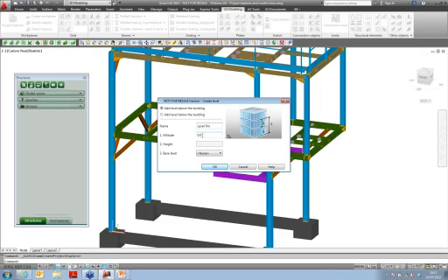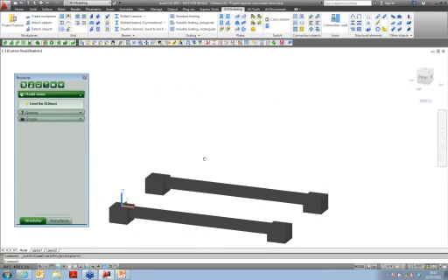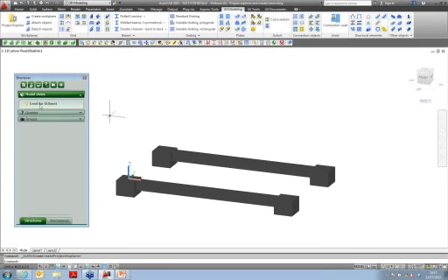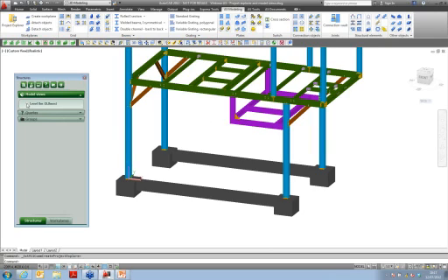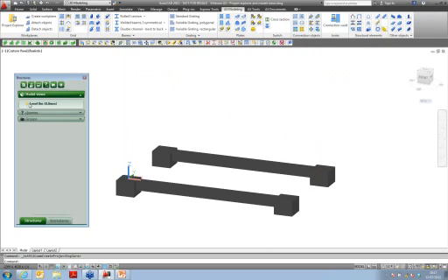Okay, so just define here the altitude, define a name, press OK, and then a level is created. You see here in the Project Explorer, the level appears automatically. It's activated and displayed. But if you don't want to display only this level, you just click here on this bulb. So you can have only elements depending on this level be displayed. It's easy to work on them.